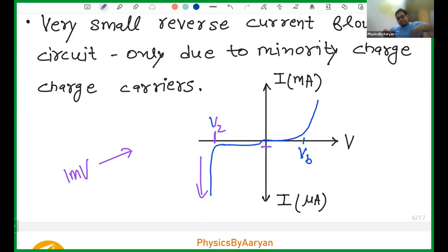And even if he takes the 3 ampere, his voltage is not going to change, because current can change, but voltage will not change. So the Zener diode will remain at the same voltage, and whatever extra current is coming, it will absorb that, and the current through the load or the device will remain the same. That is how a Zener diode works.